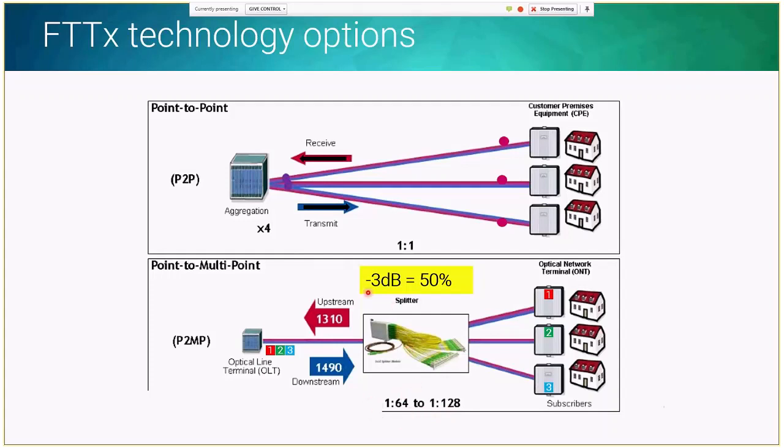And this is the rule of thumb: if you have 50% of the power, which is 1/2, so if I have one fiber coming in and two fibers going out, this equals 50% of the power for both of the legs, which is minus 3 dB of the incoming power per fiber. So if you're going to go for 1/64, we can keep dividing by 50% until we find the relation. This is one of the takeaways that I would like you to take today, just as a rule of thumb.